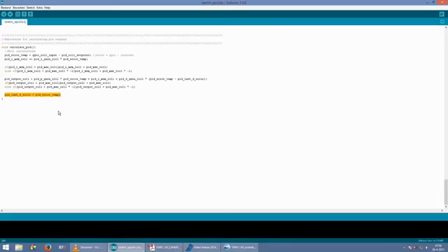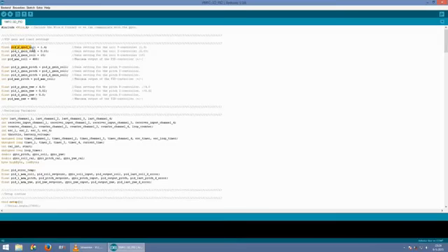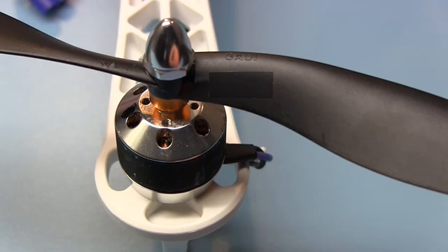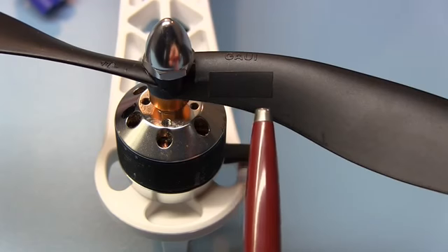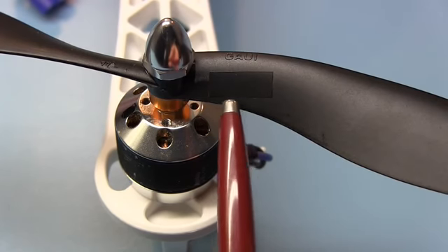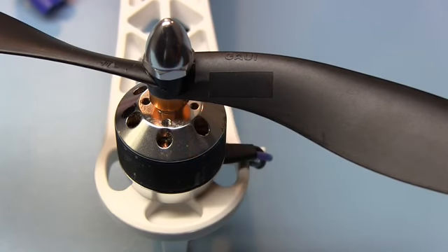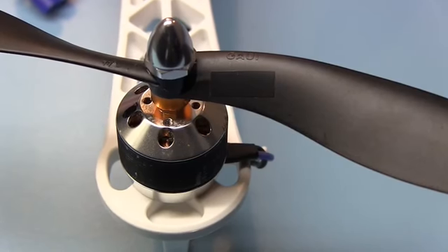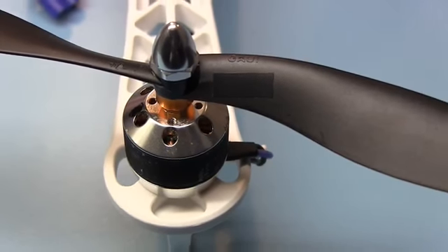Now I will show you the basic steps on how to set up the PID settings of this particular multi-copter controller. Now if you are lucky, this might also work on other flight controllers. But my main goal is to set up the YMFC 3D flight controller. Before you start, balance the motors and props to get the best results. You can use the program that I wrote for part 4 of this video session.